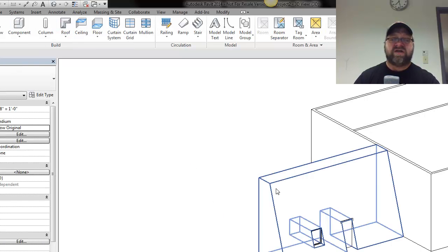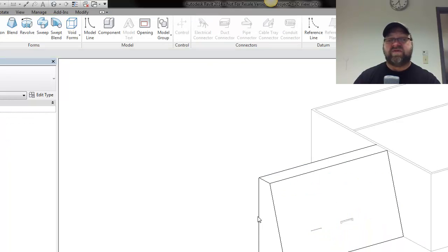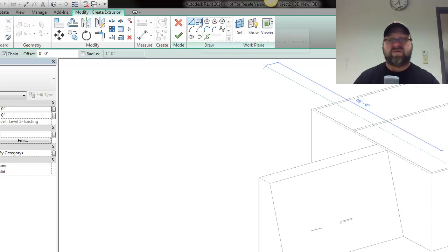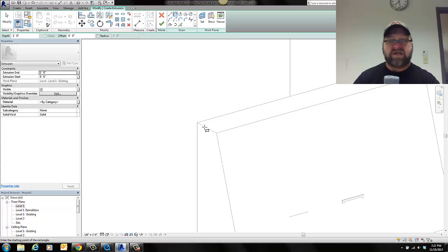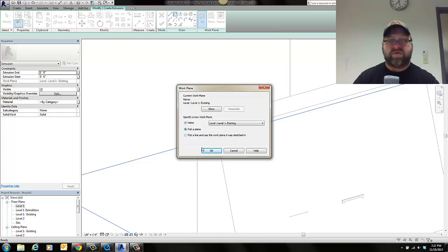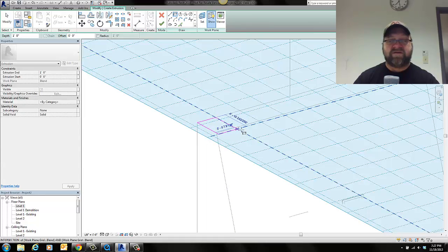There's a few shapes you may not be able to get to, and of course it doesn't. I just did one thing, but you can always come back and you can add other pieces. So if I wanted other extrusions on top of this, maybe there's these things that sit up on top. Let's do this. Set my work plane. Let's try that. There we go. All right, so I want to put something up on top here. So I can build the little piece up here. So there's no reason why you have to be limited to one solitary piece of geometry. You can add other things in.